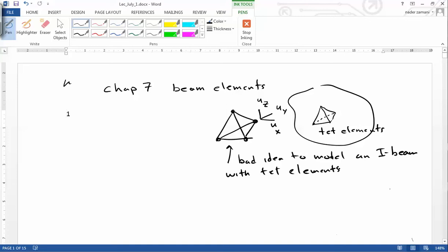That means that it's going to be very small elements there. And because the length of the I-beam is quite large, then we'll suddenly start dealing with potentially 100,000 elements to analyze an I-beam. There are other structures where using tet elements is not useful. For example, if you take the frame of, let's say, a skyscraper or a high rise, these are made of lots of beams welded together and bolted together, etc.